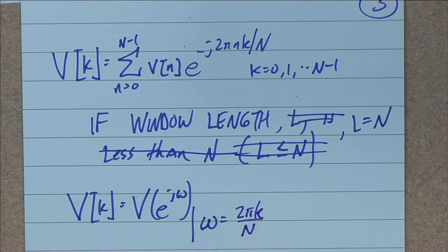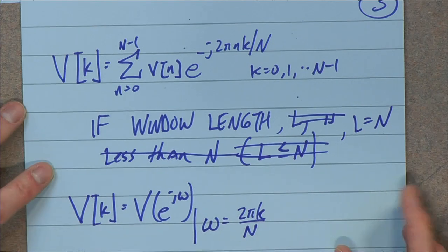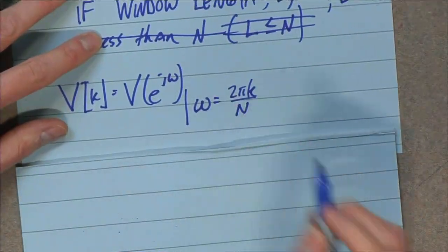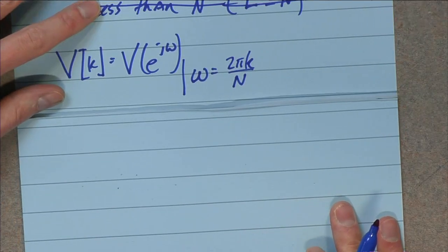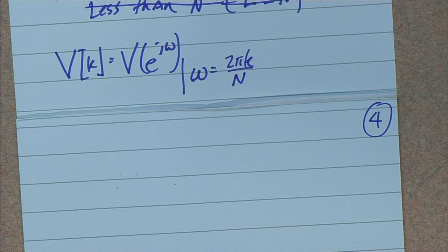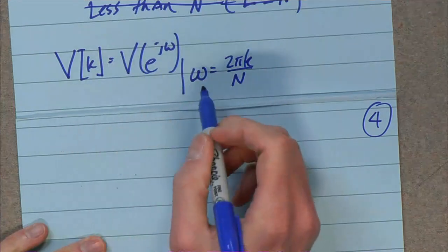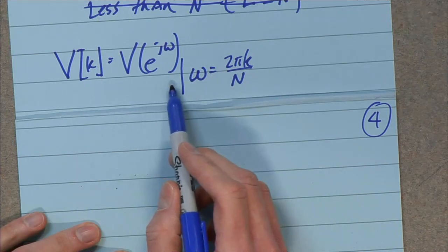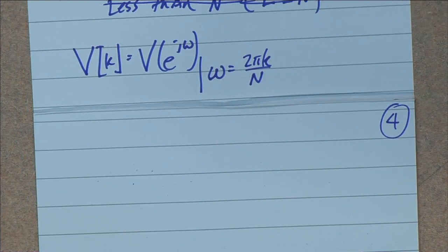So this is all kind of a review, but now what are the spacings in both domains? In the frequency domain with omega, we've already got that. We just wrote it down. It's going to be 2 pi over N. But let's convert it back to capital omega, or continuous time, because usually what's happening in the physics world is impacting capital omega. That's what you really care about. But what we're playing with is the sampled data, so we have to map that back.